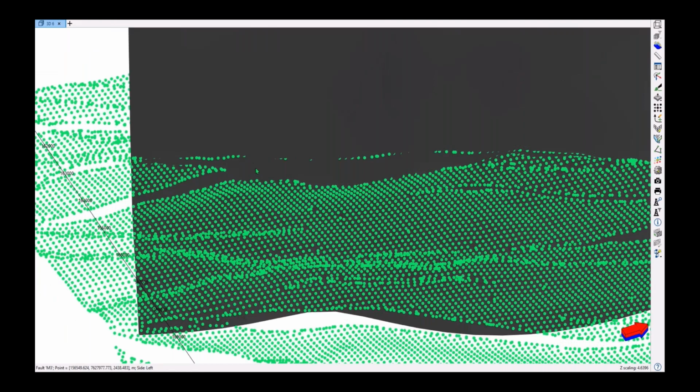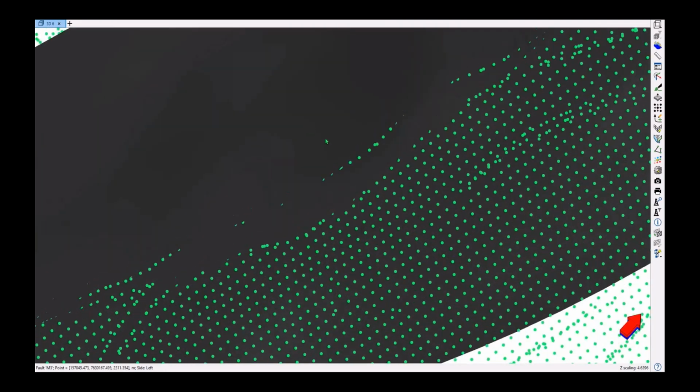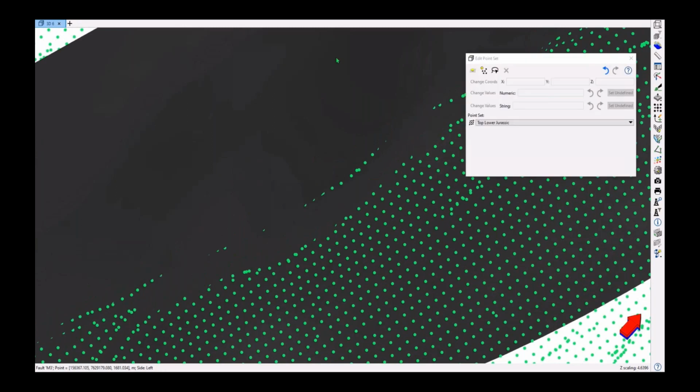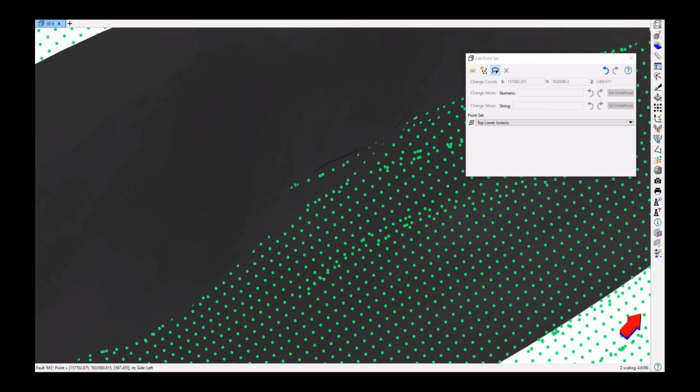We're now going to remove some of the drag zones from our data. So you can see here I have some wrong-sided data on one side of my fault. I can then go in and use this little lasso tool to drag around here. And when this data goes through to the gridding, if we don't want to get any drag zones, we can come in, remove some of the erroneous data, just like this, and just delete them.